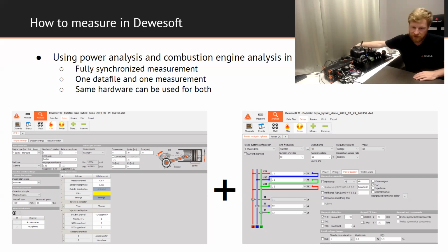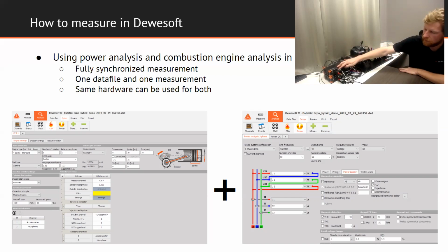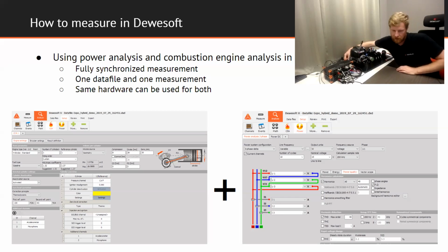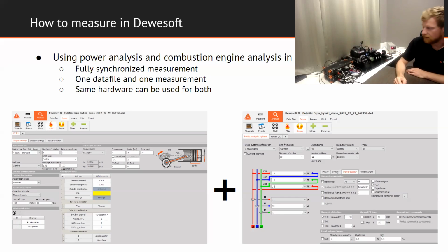And we have on the back side of the engine an encoder mounted, which is connected to the counter input. We have, of course, also possibility of analog input connection of the angle sensor. And on this engine, we have two additional sensors mounted, just as an interesting fact. So one accelerometer on the combustion engine, and we have here also one microphone, so we can measure the noise of the exhaust that the engine makes.